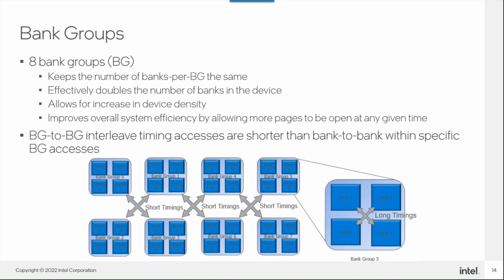Apart from that, I don't know, Bhumika, do you want to add? No, you captured the main key advantage: the timing associated with switching between banks is shorter compared to DDR4, and that saves overall performance, right? Anything else on bank groups?